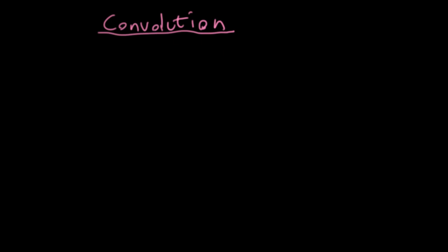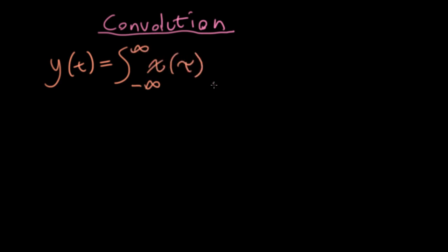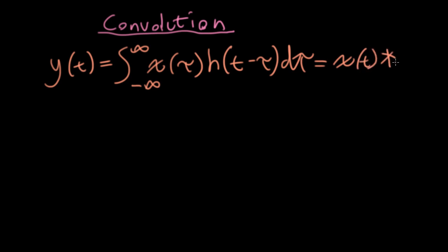of it early. So in the last lecture, we looked at linear and time-invariant systems and created a notation that said that we could find the output of a linear time-invariant system by integrating the input x of tau against the impulse response, here labeled h of t minus tau, integrate over tau, and we would write this as x of t, this asterisk symbol, times h of t.